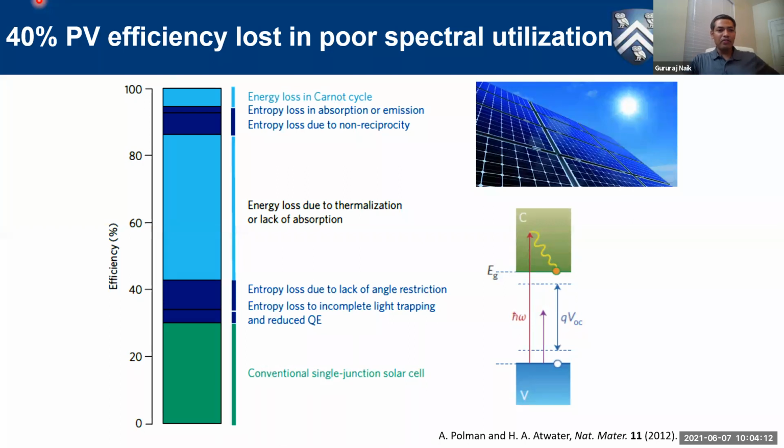If you just look at, for example, the current efficiency of photovoltaic cells, we see that the efficiencies in market, for example, the silicon solar cells, are just about 22%, right? So why is it that low? Can we bring anything better? And the answer is yes, of course. You can change the material from silicon to gallium arsenide and your efficiency increases to 28%. And instead of gallium arsenide, you can also have multiple junction solar cells, where each solar cell has a different band gap, and you can boost the efficiency.